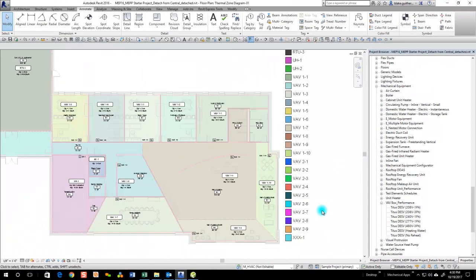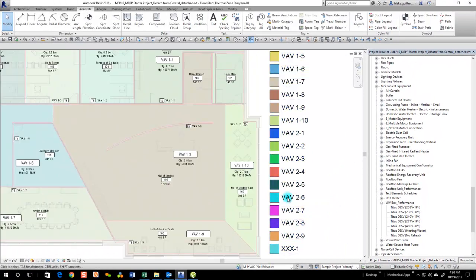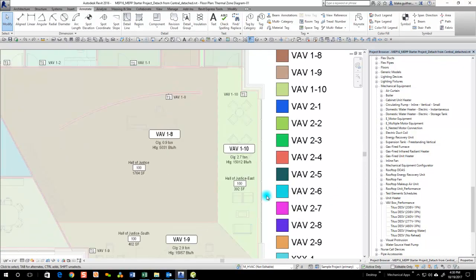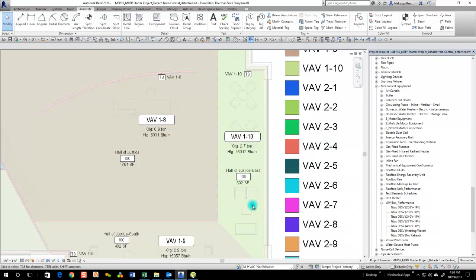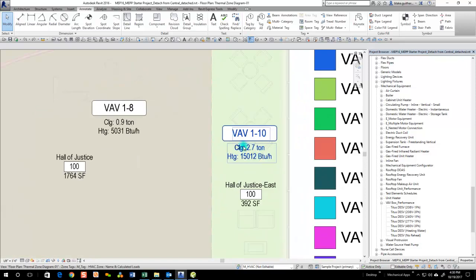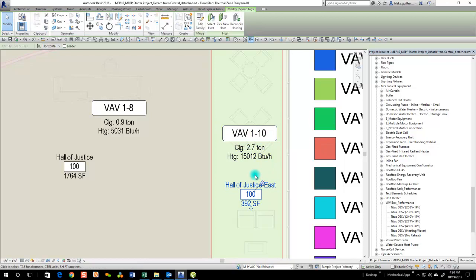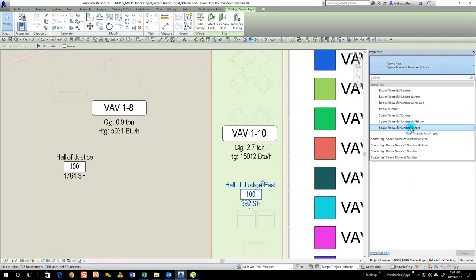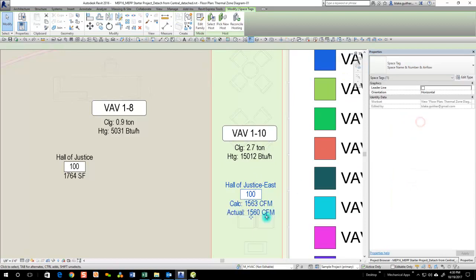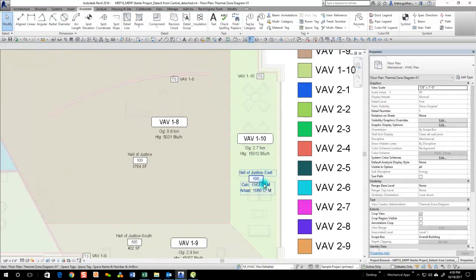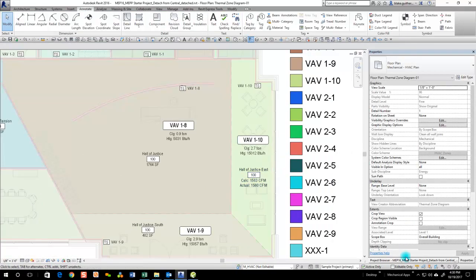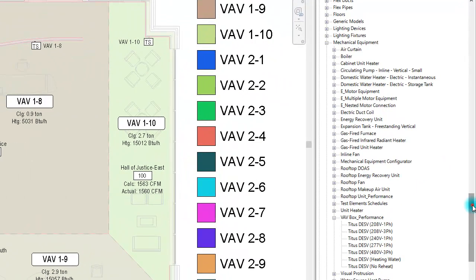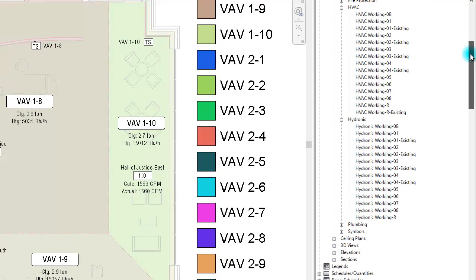All right, so the process. The first step is getting your zones done in Revit, getting the calculations done somehow, whether exporting to a third party or doing it right within Revit, but essentially getting load data in here, because this ends up driving all of the stuff downstream. So we also have calculated airflows. Step one is getting your loads done, just like any other project. Step two is going to be getting airflow at diffusers and placing diffusers.